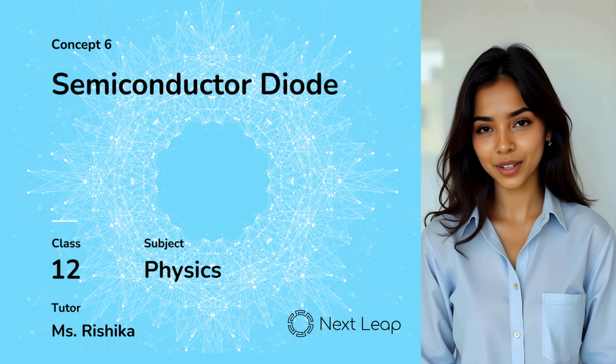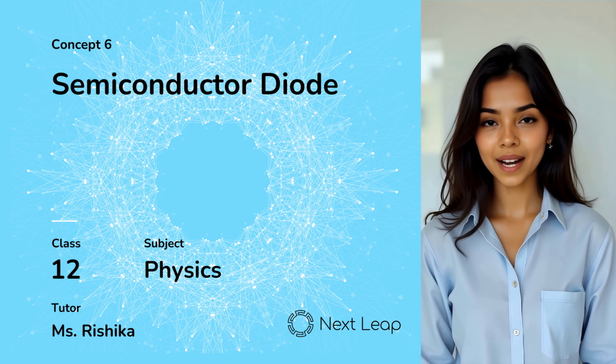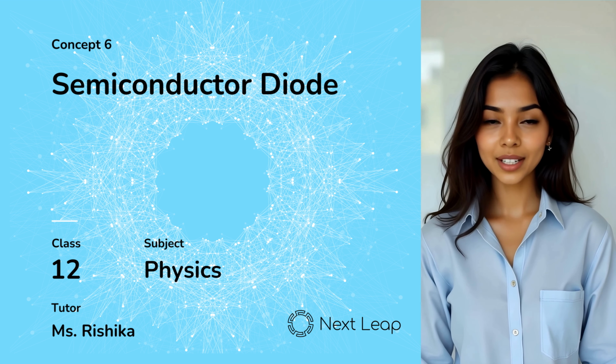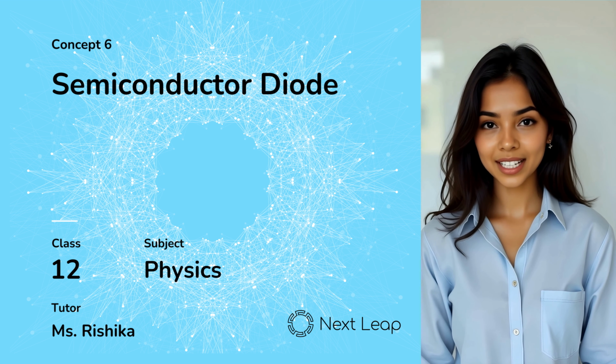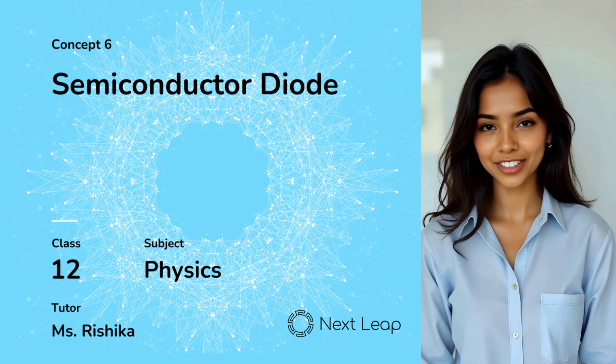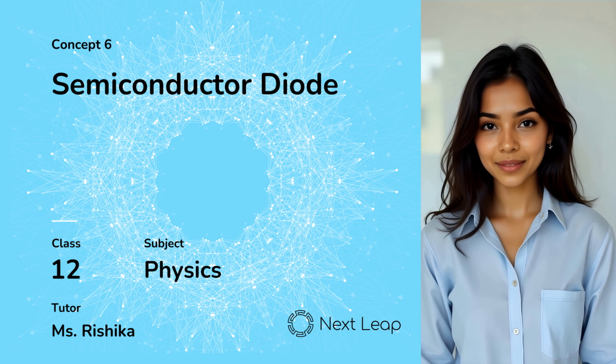Now, the behavior of this smart little device is defined by a beautiful formula. I is equal to I naught times the quantity e raised to the power of qV divided by kT, minus 1. Here, I is the current, I naught is the reverse saturation current, q is the charge of an electron, V is the applied voltage, k is Boltzmann's constant, and T is the absolute temperature in Kelvin.